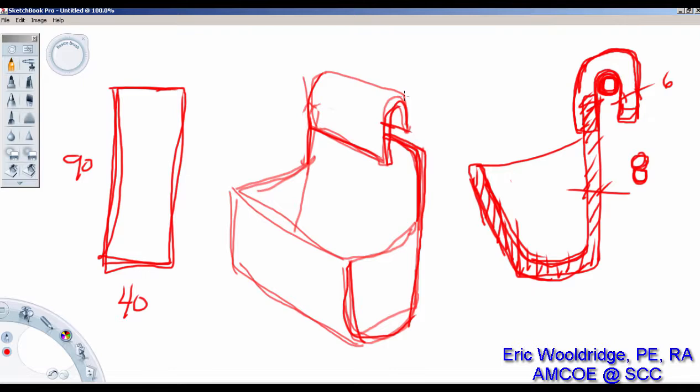And so what we have here is a very simple kind of design. It's going to be some kind of little cup system with a separate piece. You'll notice that I have offset the hook in the design so that it can print from this direction without having to have any support material. And we'll probably have to do something down here a little bit for that as well, but we'll take care of that in a few moments.